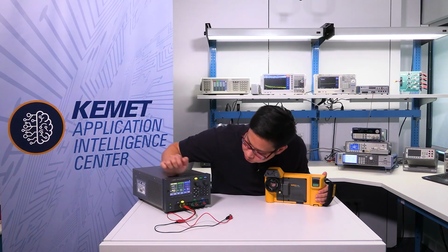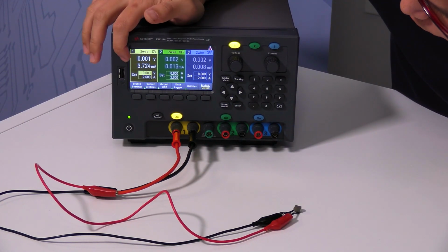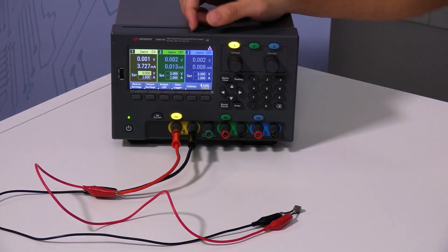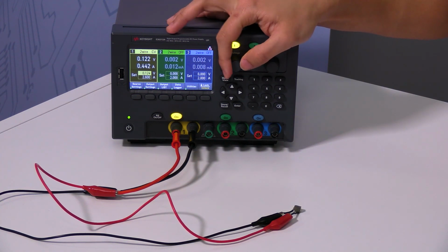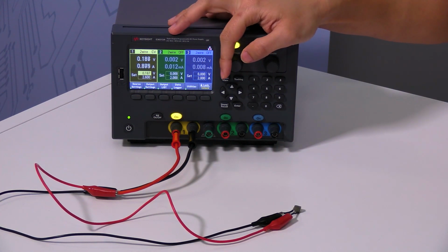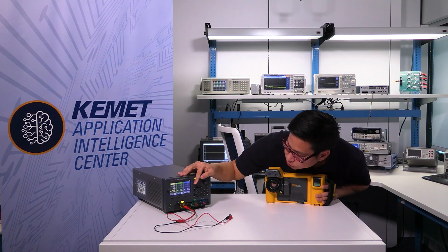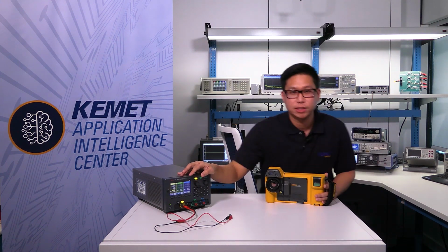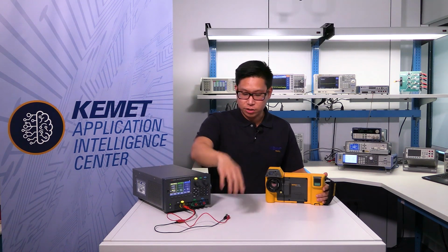Yeah, so first you want to set your current to 2.6. And I'm going to set my current to 2.6, and we're not going to get the current draw that we need, but if we slowly increase the voltage, we'll notice the current start to increase, because you're going to need voltage if you want current. So in my case, once I set it to around 0.7 volts, I'm going to get a constant 2.6 amps going into this inductor. And it's already starting to heat up